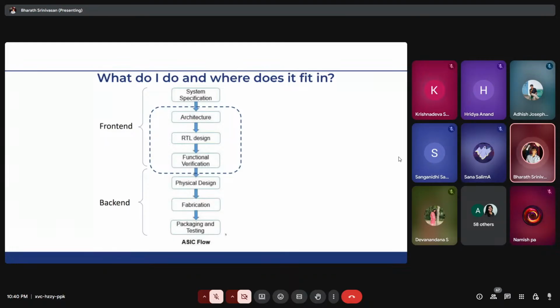In between PD and synthesis, there is DFT, design for testability insertion. So there are a lot of things that happen in between. So make sure you have a detailed understanding of the ASIC design flow, and maybe not much is required towards fabrication, packaging, and testing. That is mostly fabrication, packaging, and testing. Packaging, at least, is mostly chemical engineering, fabrication as well, but that is okay.